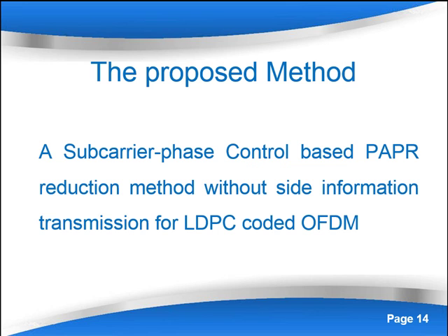For example, based on reliability information of each received bit, a limited number of candidate phase sequences are selected from all possible phase sequence patterns, and likelihood values corresponding to these candidate sequences are calculated to estimate the selected phase sequence.